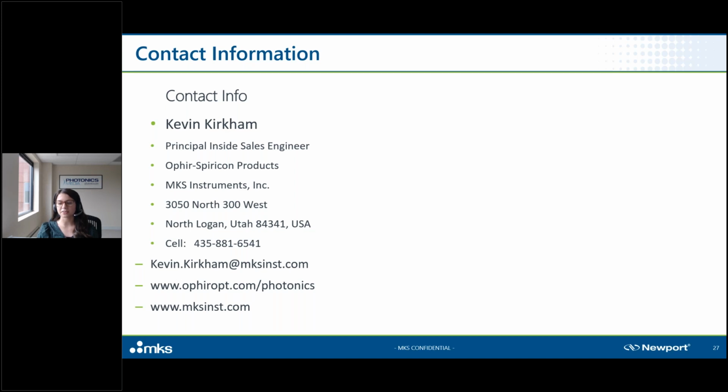All right, thank you. This next question is, can I measure infrared and fiber lasers with the same equipment? Yes, in most cases you can. With the possible exception of the microbolometer camera, all of these technologies will also see the 1 to 2 micron spectral range.